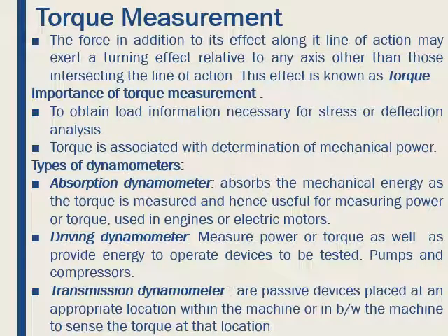A force, in addition to its effect along its line of action, may exert a turning effect relative to any axis other than those intersecting the line of action, and this effect we call torque. It is important especially to obtain the load information necessary for stress or deflection analysis. Torque is generally associated with determination of mechanical power.